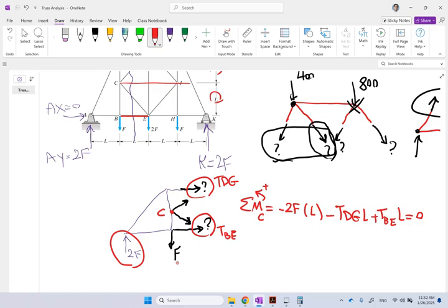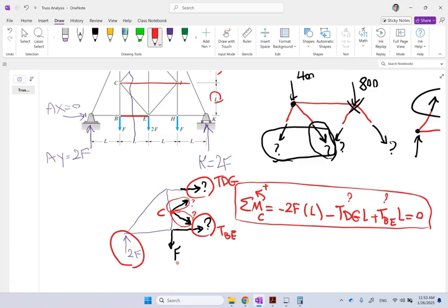And now if you look, these two have X forces only, and these two have X and Y forces. So if I write the X equation, these two will come in, which I don't want to come in because I have 4 unknowns. If I write Y forces, then the unknowns will not be coming in. So you see here that cut gives me one good equation, which has only 2 unknowns in it. That's not a bad equation. But the rest of this FBD is not going to give me what I needed to get.